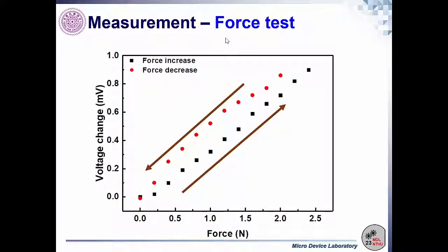Since the polymer is a critical and inevitable component frequently used in tactile sensors, we also characterize the force response when increasing and decreasing the loadings. The variation between the two response curves is mainly due to the hysteresis effect of the polymer, which should be taken into consideration for future system signal processing.